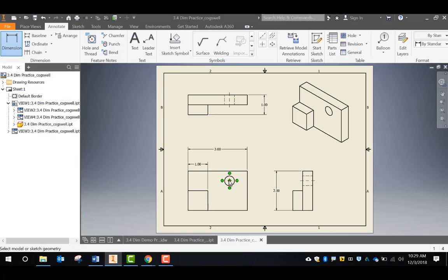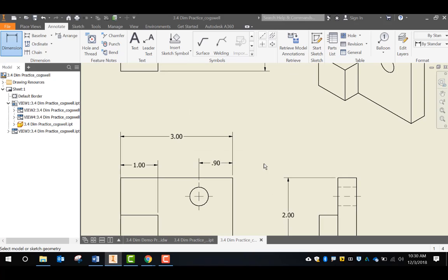I'm also going to place a dimension from the center mark to the right edge to indicate the location of that block. So I'm going to start with my center mark in the center and the right edge and drag up. And you'll also notice as soon as I've done that, a dotted line goes from the dimension I'm working on to the number 1 dimension on the left there. That's just to help you line things up to keep it nice and clean. I go ahead and click OK, and that mark is placed. It actually looks like it's a little bit higher, and it should be.